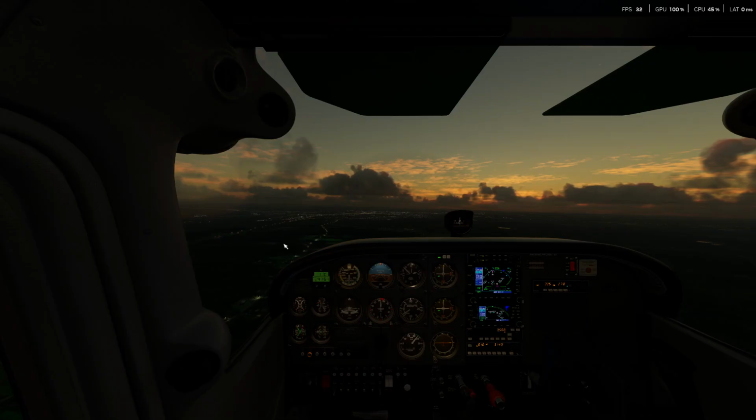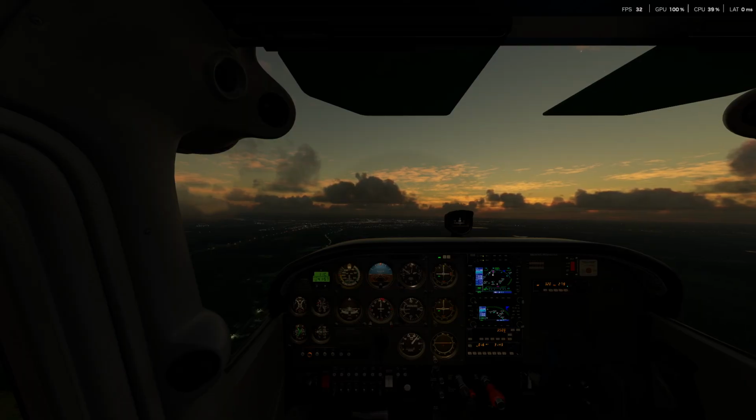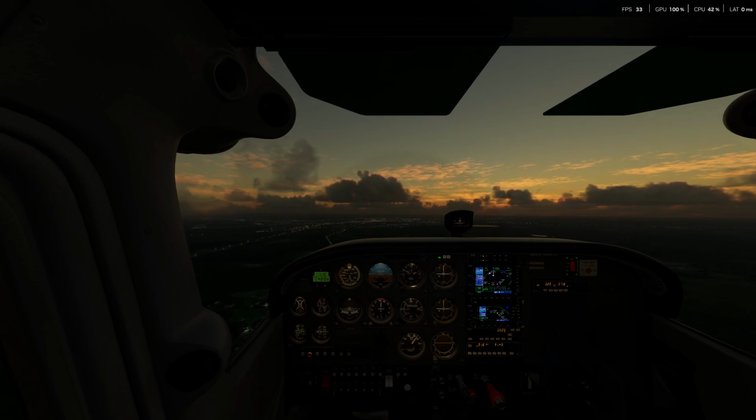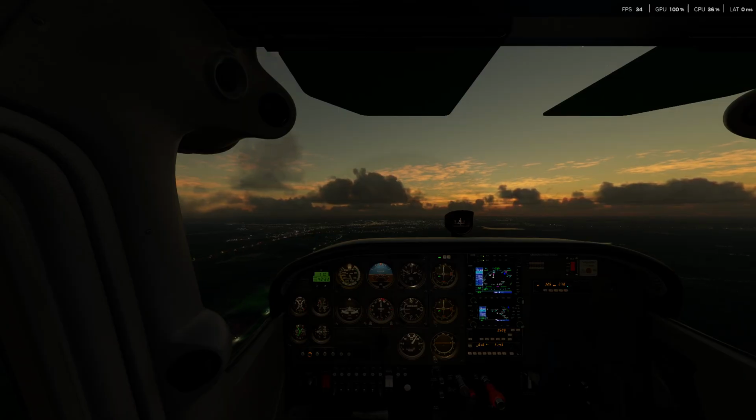So we're going to level off at 1,800 feet here. We'll raise the nose just slightly for our normal attitude for straight flight, and I'm going to trim out the forces there for that zero feet per minute. Perfect speed. I don't know why, but it's actually hard to trim out the sim. Get good, as they say.